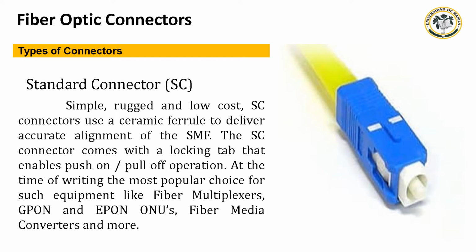The first type of connector is the standard connector or SC. Simple, rugged, and low-cost, SC connectors use a ceramic ferrule to deliver accurate alignment of the SMF. The SC connector comes with a locking tab that enables push-on or pull-off operation.